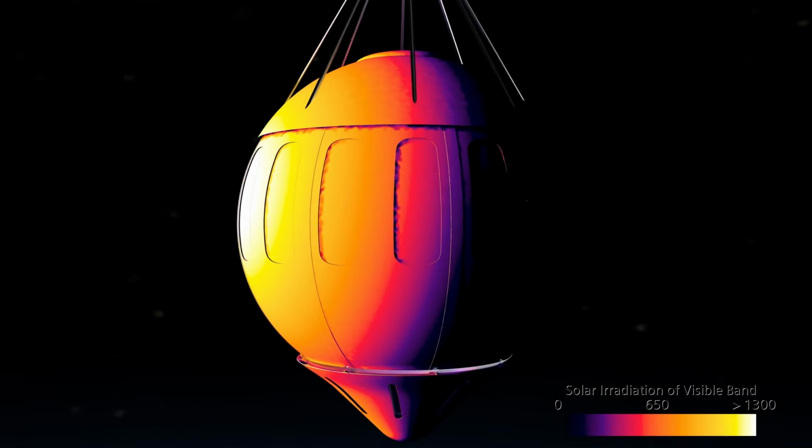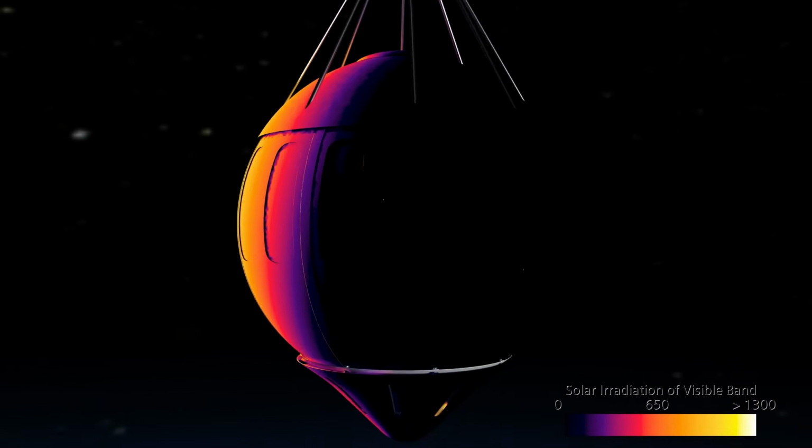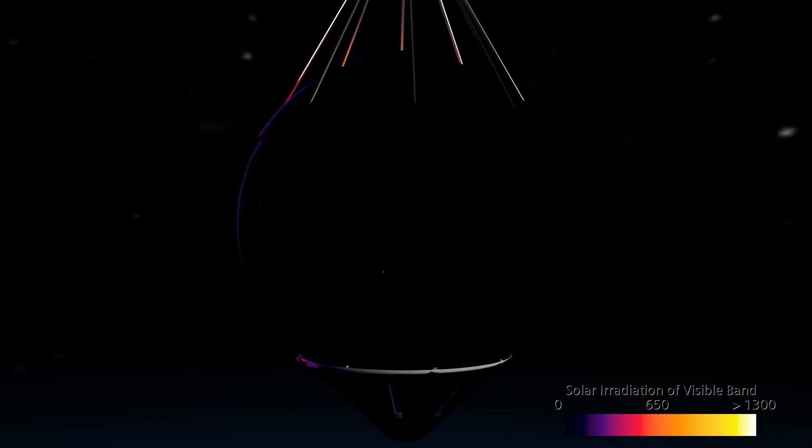The Photon Monte Carlo model is the highest fidelity solution approach that we have implemented in Simcenter STAR-CCM+. It has the most accurate modeling of complex phenomena like absorption and scattering of the radiation source when it interacts with the participating media. In addition, compared to the DOM that solves the radiation only on a fixed number of directions, the Photon Monte Carlo model solves radiation in any direction using a statistical approach.